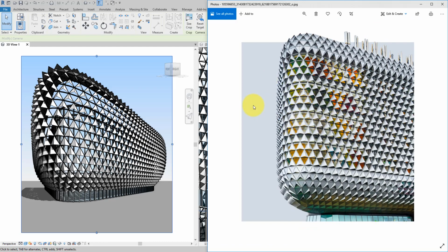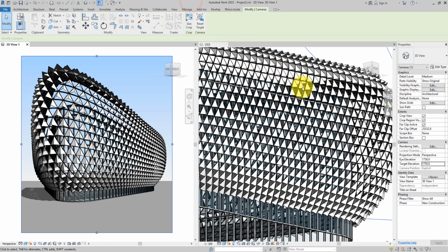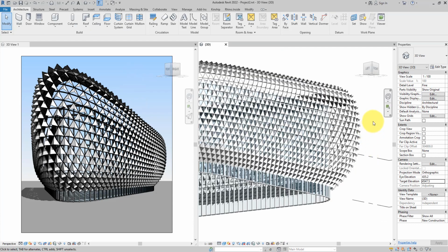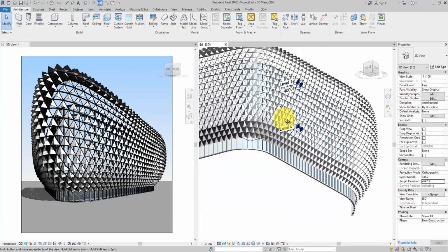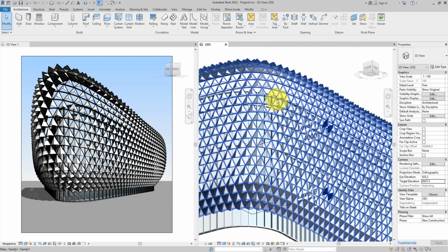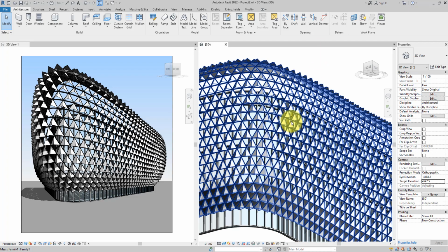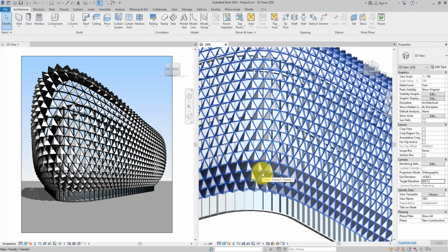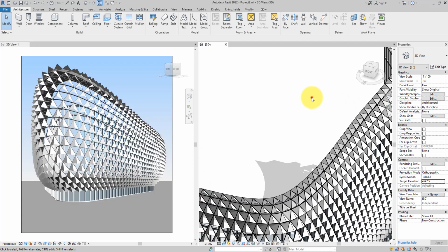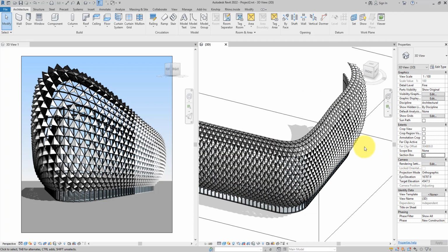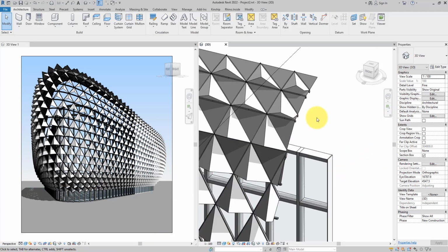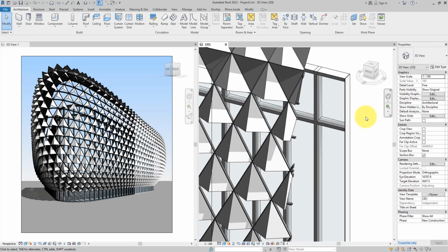I have made here a copy of it in Revit 3D. As you can see, that's the perspective view, and here I have the same system I can see from any angle. And as promised, you have here in the middle section of the facade open panels, and then at the bottom and on top, you have these gray panels that are closed, just like the design we saw in the photo. To see it clearer, I can also have maybe a quick section box and then bring it this way. As you can see there, closed panels combined with open panels make this facade really dynamic.